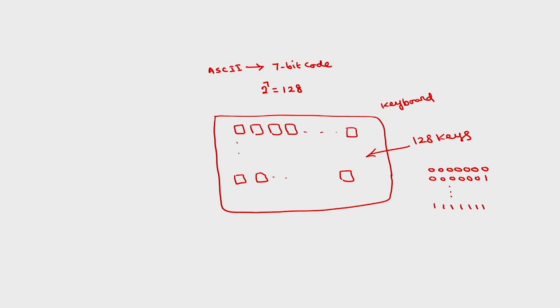So in the case of ASCII code, 0 is represented by, this is standard, 0 1 1 0 0 0 0, which is 30H. This is in hexadecimal, you can even insert a 0 here, so this will be equivalent to 30H. 1 will be represented by 31H.